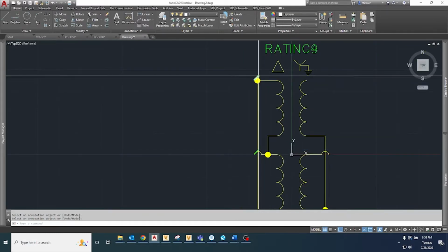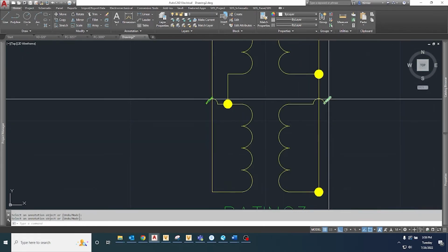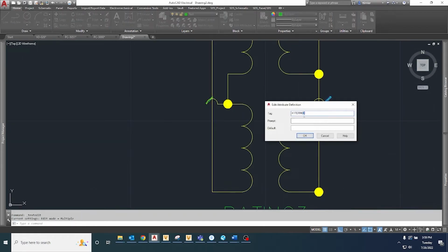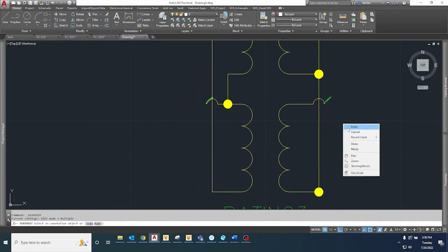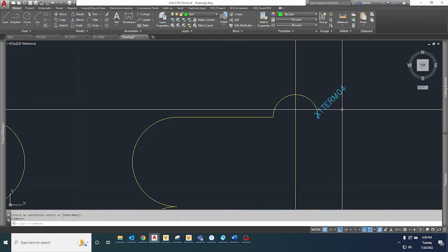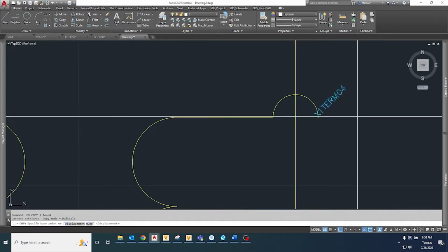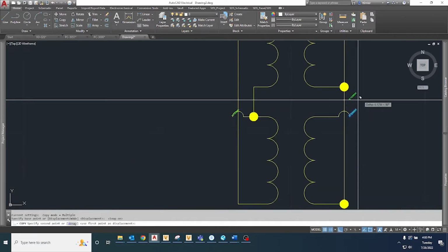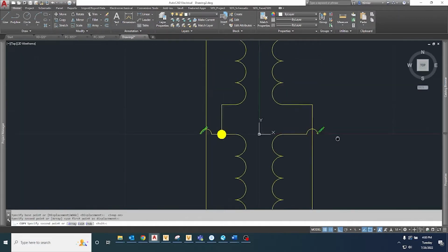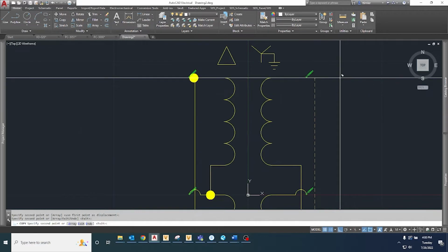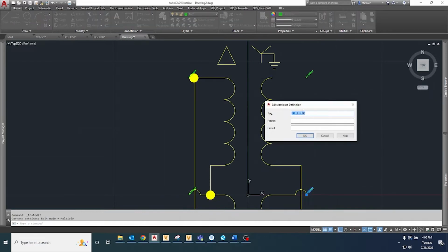When placing the connection point attributes for this symbol, I want to maintain the same term attribute and connection point attribute positioning as the 1-line transformer used to create the 3-line symbol. The reason being, when this symbol is complete, its symbol name will carry the same 5-character file name prefix as the 1-line symbol it's based on to denote a relationship and orientation between the two symbol types within our symbol library.